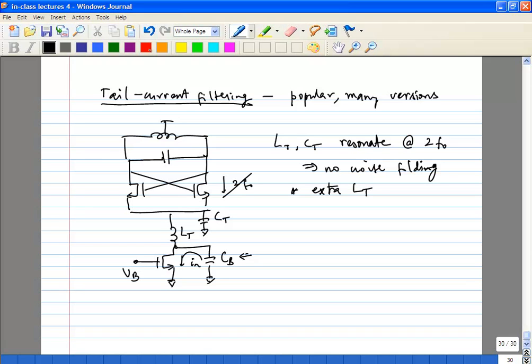So the drawback of this is that you do need a second inductor, so you are going to use some significant amount of area. But it only handles the second harmonic, not the higher harmonics. Yes, but remember when we discussed the gamma function, which is the ISF, the Fourier series coefficients? They actually go down for any real oscillator as you keep increasing the harmonic number. The noise which folds down from the harmonic number keeps going down.